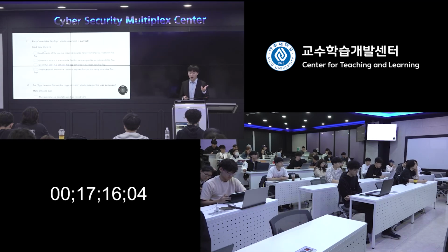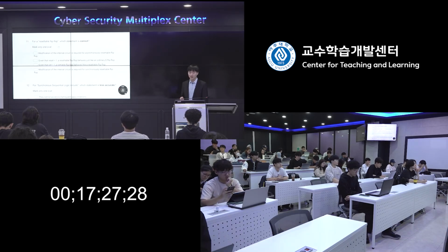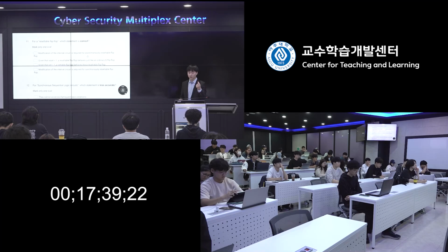So with this in mind, if you remember the function of this resetable flip-flop, then we check the options. Modification of the internal circuit is required for asynchronously resetable. This is what we shared, right? When we learned the resetable flip-flop, it introduced the synchronous and asynchronous concept. Naturally, the resetable flip-flop is a synchronous design. If we want to make it asynchronous, we need to modify the internal circuit. Then the others are just not correct.